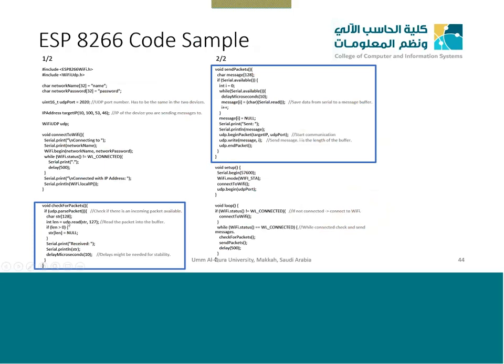This is a UDP protocol we have implemented. We just say UDP.read, and it will read the data. With UDP.begin or UDP.write, it will write the data, whatever is received or sent. So this is not very difficult to set up. The libraries are easily available, and that is all the code needed for the transmission part. Of course, when you are using Arduino for sensing as well, you will need a short code to sense the temperature data and then move it to this device.